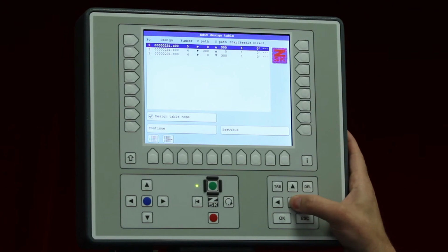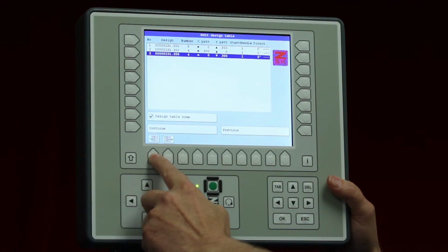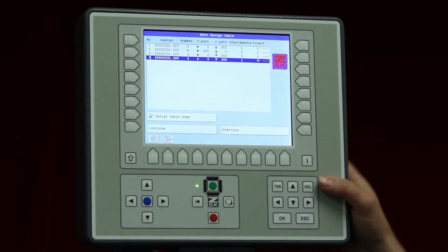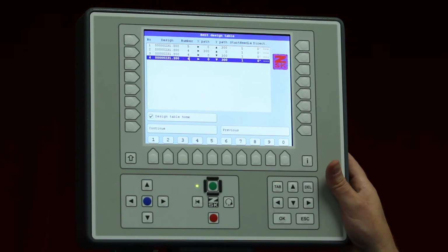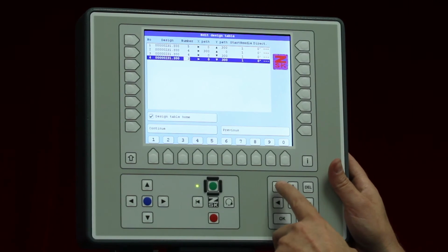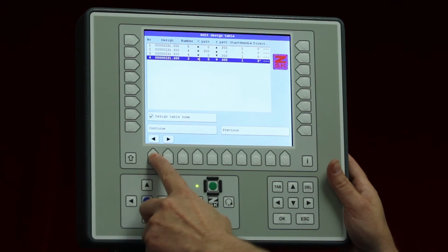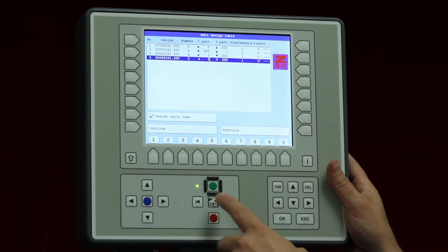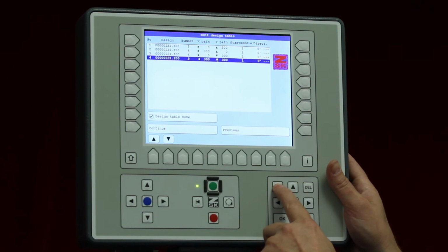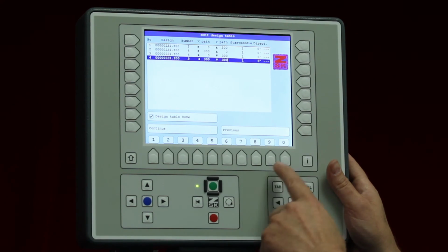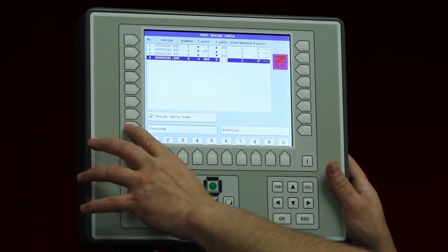And in this case, I will go now to the last line, insert another one by pressing U1. And we go again here. Then I have to copy now 3 parts of it, tell him 3. And I would like to copy it to the left side. I use the arrow to the left. Tell him I want to have 300 increments. And I don't want to copy it vertical, up and down. Just make here a 0 and continue.